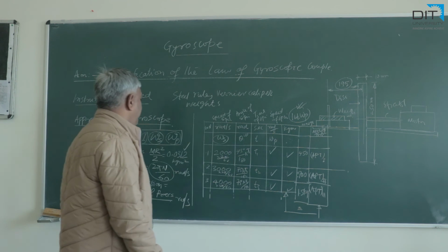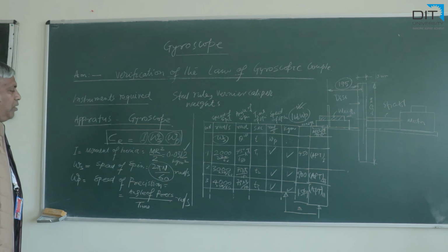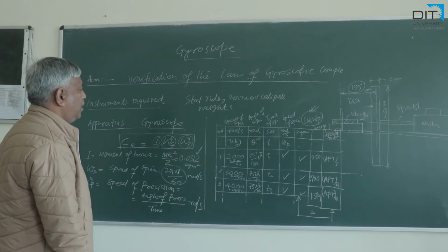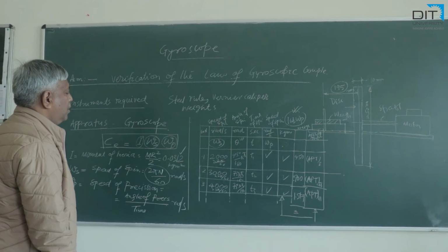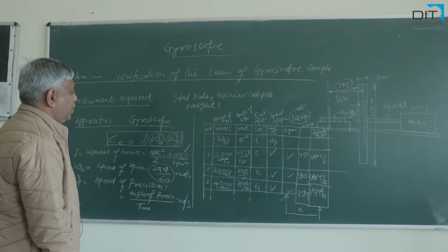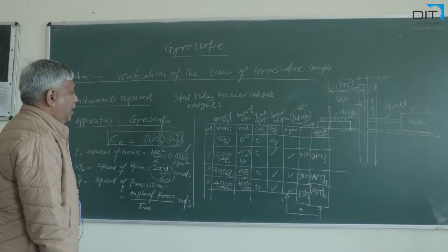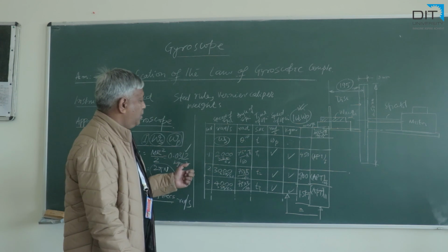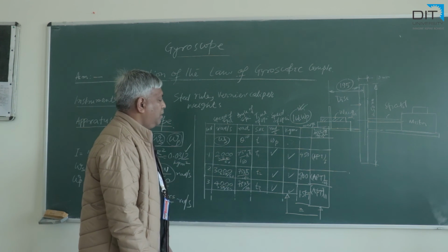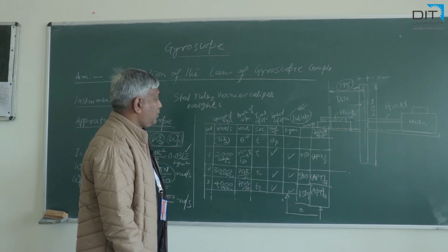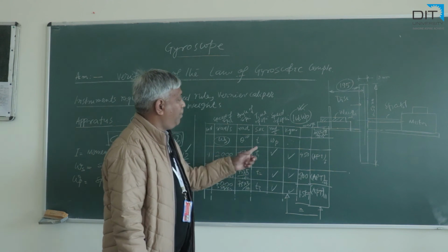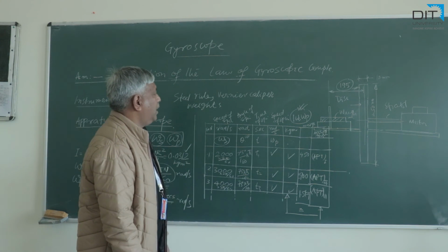And to do this experiment, we should take some precautions. The speed should be increased very gradually. We should not touch the setup while working, and the calculations should be done very precisely, because our purpose is to compare the actual applied torque and the theoretically calculated torque.